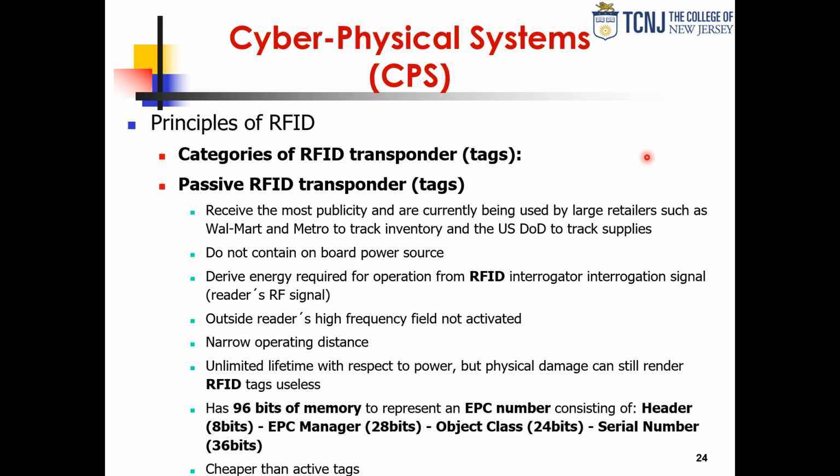So these are the ones that when the reader part is constantly broadcasting a signal, that when it matches the signal that the RFID coil is tuned to, that excites that coil, and the RFID comes up, it charges the capacitor, does the energy harvesting, stabilizes its power source, and then turns on the receiver and listens for the RF part of the transmission. Am I being queried?